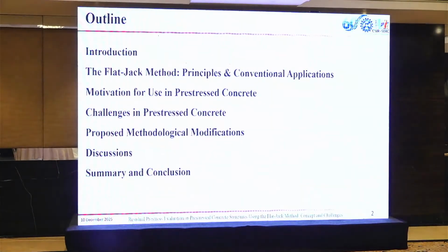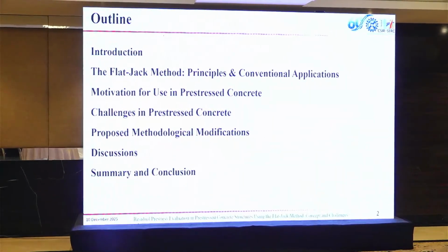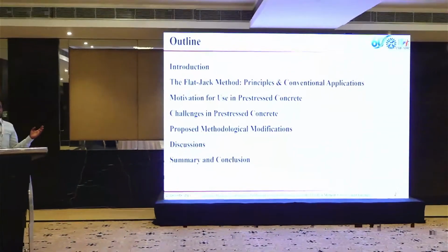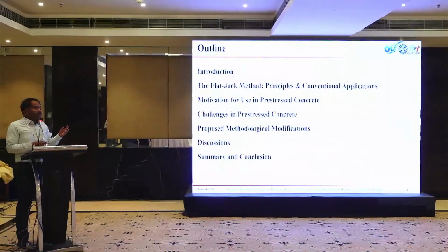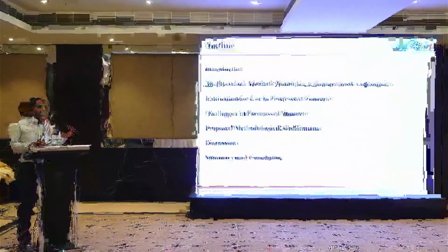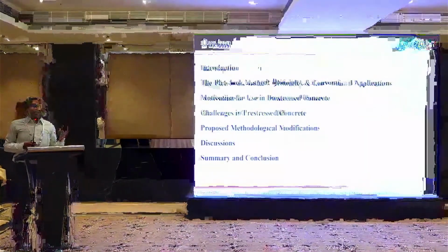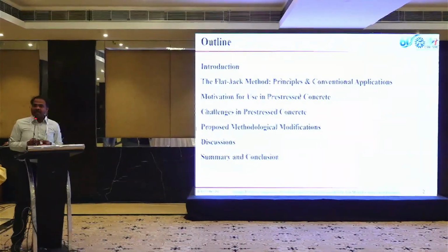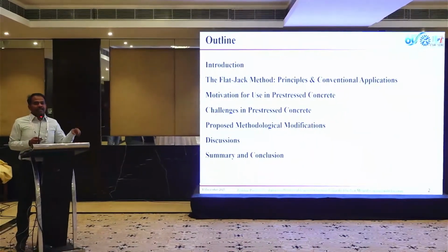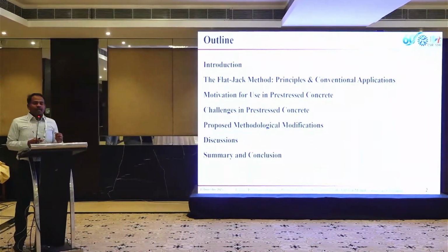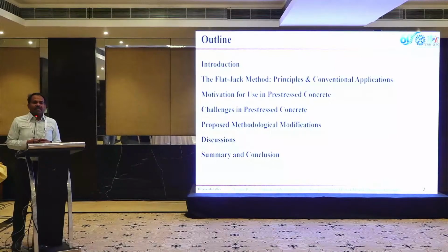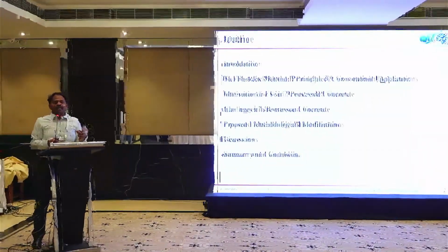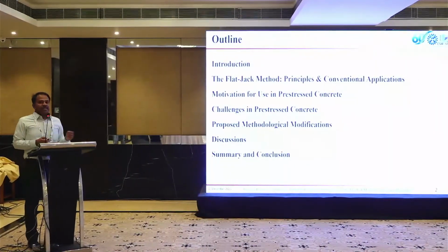So my outline of the presentation will be like this. First, what is residual pre-stress measurement, and then the flat jack, its working principles and its applications. Then what is the motivation to use this flat jack in pre-stress concrete, then the challenges faced using the flat jack in pre-stress concrete, and what methodological modifications have been taken towards those challenges, and finally discussions on the studies conducted, with the summary and conclusion.